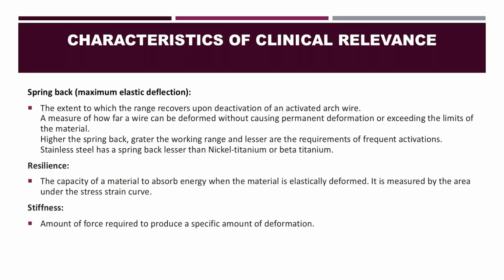Characteristics of clinical relevance. Spring back, that is maximum elastic deflection, the extent to which the range recovers upon deactivation of an activated arch wire. A measure of how far a wire can deform without causing permanent deformation or exceeding the limits of the material. The higher the spring back, the greater the working range and the lesser the requirement of frequent activations. Stainless steel has a spring back lesser than nickel titanium or beta titanium.